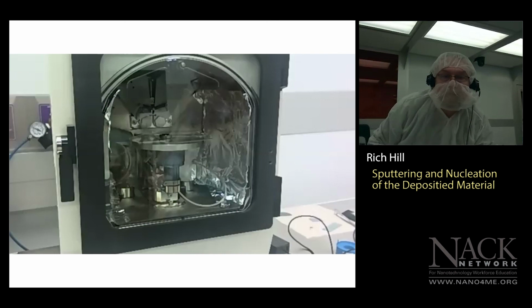So it'll deposit carbon with a thread. We have a carbon thread that we thread inside the Leica here. Then we close it up, put it under vacuum, and then it will send a charge through the thread, causing it to flash. And when the thread flashes, it rains the carbon down onto our sample.